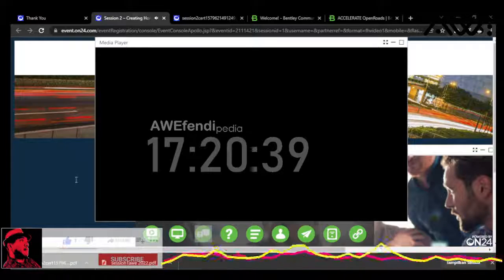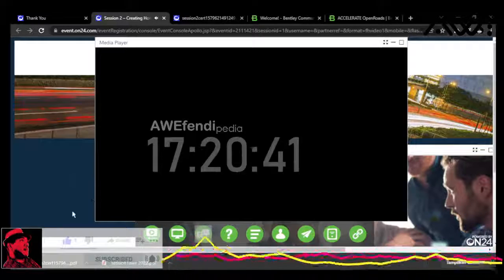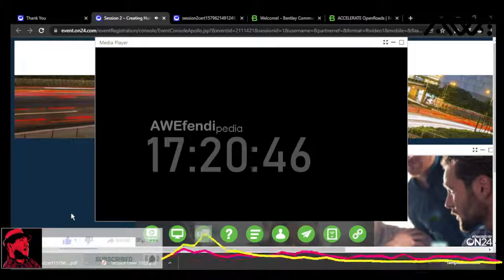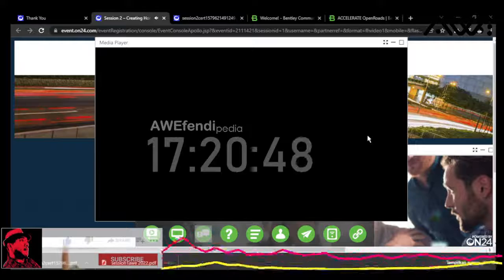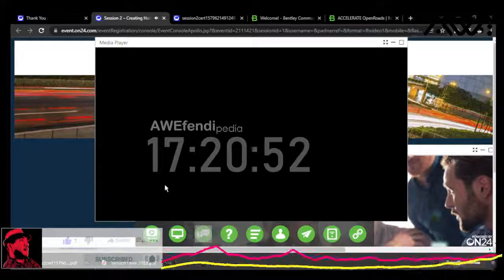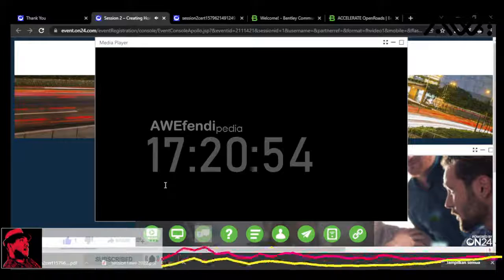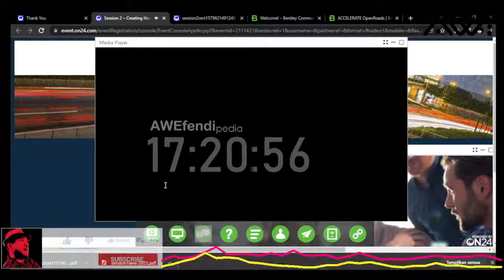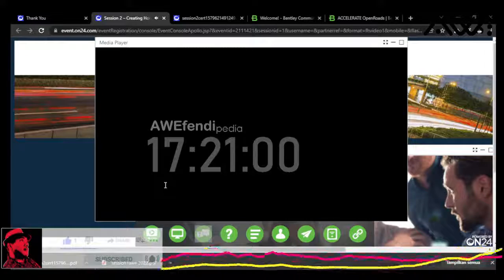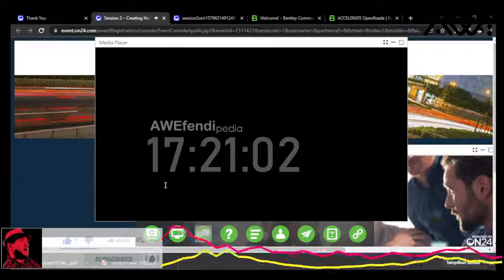And you'll notice as you draw that element, you've got heads-up prompts. You'll notice those on the cursor. And I'll try and explain those. On those heads-up prompts, number one, you can key into the highlighted field, as well as the arrows indicate that I can move between information, left or right. So I click the left arrow or the right arrow, and it tabs me through distance and direction that I can use to input data for this particular element.